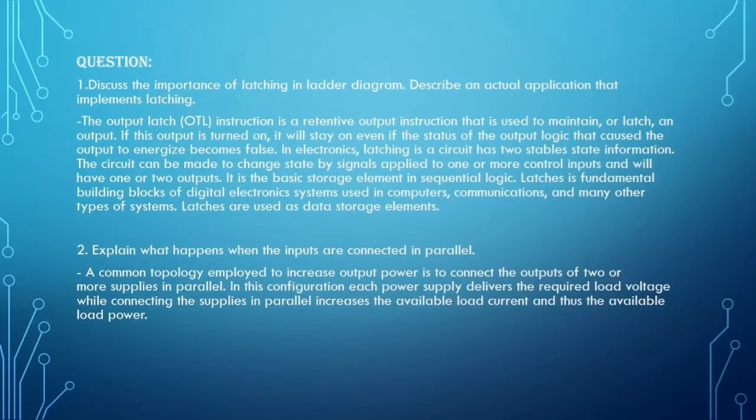For question number 1, discuss the importance of latching in ladder diagram. Describe an actual application that implements latching. The output latch OTL instruction is a retentive output instruction that is used to maintain or latch an output. If this output is turned on, it will stay on even if the status of the output logic that caused the output to energize becomes false.